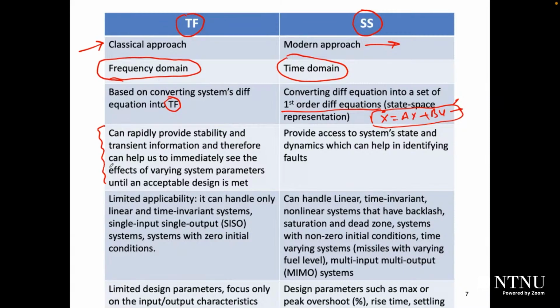But working with a state-based representation, it provides access to system states and the dynamics, which can help in identifying faults. It gives us more abilities, in fact, for making more complex stuff. We can design really more complex systems, and also maybe we can design systems which can detect faults in your system because we have states and we can identify states. It's like a patient in a surgery room, for example, and you can see many things, right? When it is in time domain or in state-based representation. So at least we can identify faults.